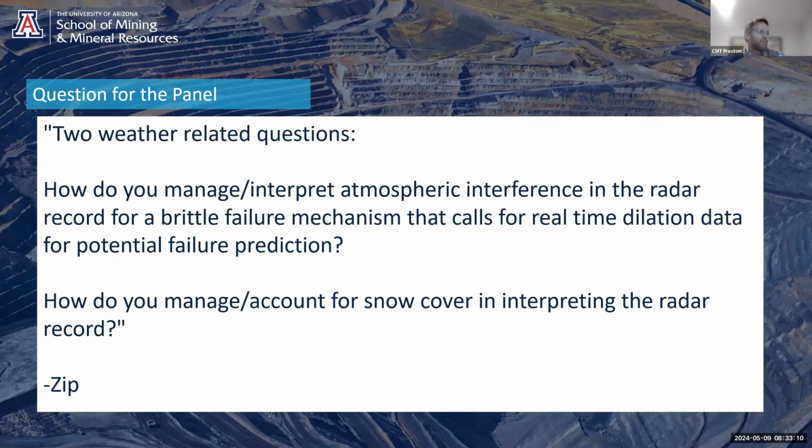But maybe hours before, there was not much or no sign at all of a brittle failure happening. So how soon is the question it comes down to, because you want to know as soon as possible that it could be happening. And the more noise you have in your data, generally the later you're going to find out that failure is happening, because the early movements of the mechanism are going to be hidden inside some of that noise initially. So understanding how much noise you have at the position where you expect the wedge failures, and then how much time that is going to give you, with your expectation of failure rates and stuff like that.